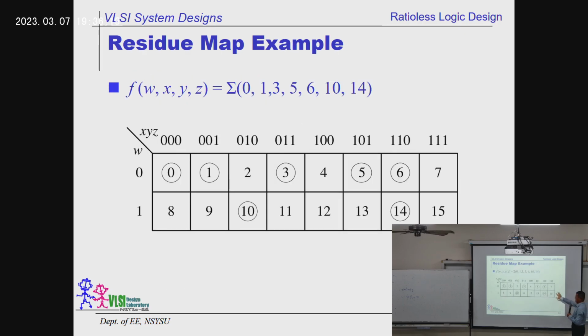Let's try this one to see what happens. Now you're going to love this one. What is the above? If you still remember, it is called the canonical form representation for a Boolean equation. We don't care what kind of variable you use. All we need is some numbers: 0, 1, 3, 5, 6, 10, and 14 as high. These are called the minterms.